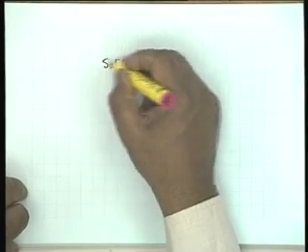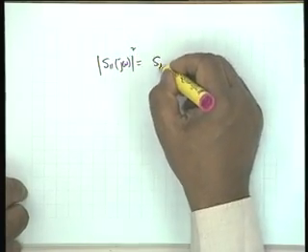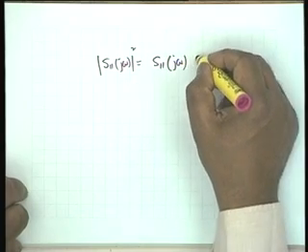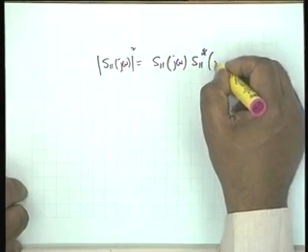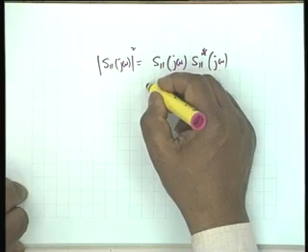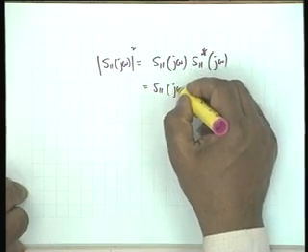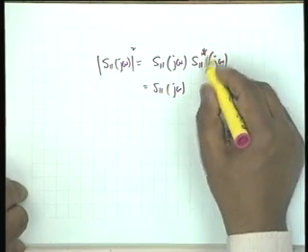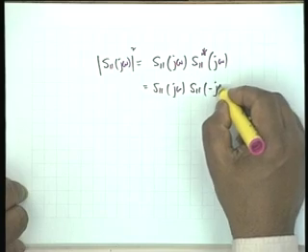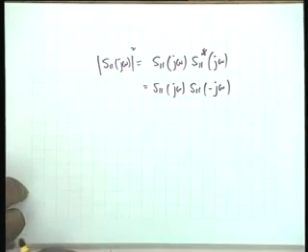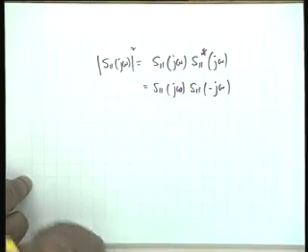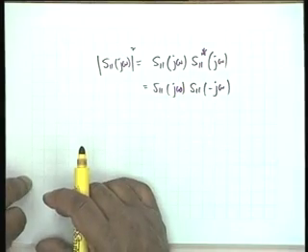Okay. The next thing that we did was, after we find |S11(jω)|², we write this as S11(jω) multiplied by S11*(jω). If S11(jω) is a real function, then its complex conjugate is simply obtained by making it minus jω. And then we said, we used the words, a big leap forward.